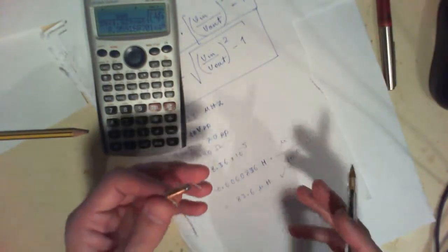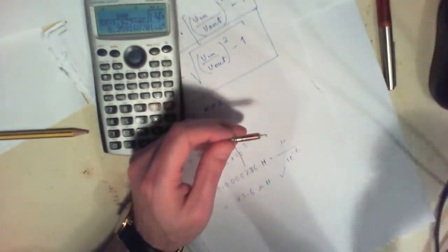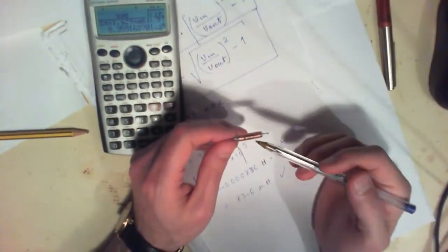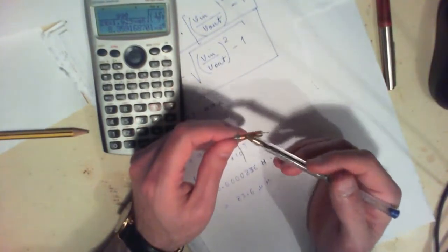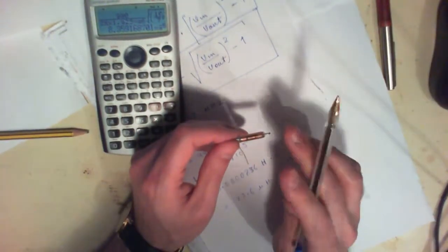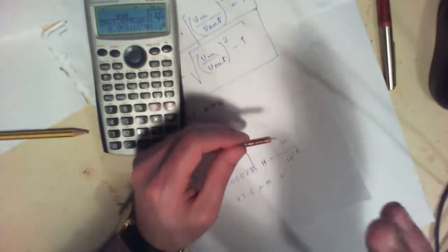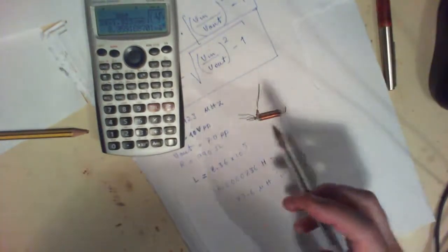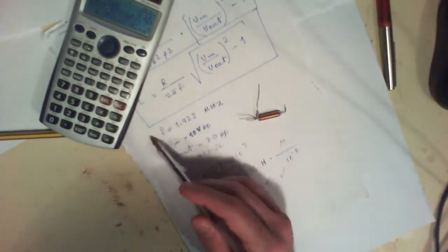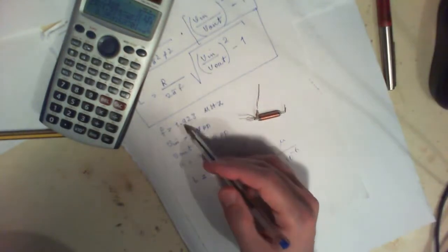So when you read something off of your oscilloscope, of course on an analog oscilloscope you cannot make very precise or accurate readings, so that would be one problem. And moreover, your signal generator is also important. Right now the frequency was about 2 megahertz, and the signal generator that I have can go maximum all the way up to 2 megahertz.